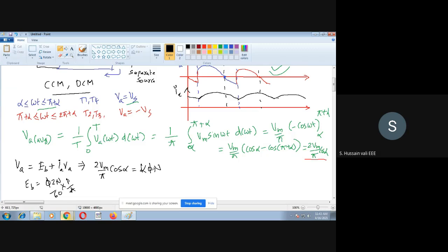So when the field is coming through a converter, then the voltage across the field may be variable. It depends upon the value of firing angle also. So better take it as k, where k is Zp by 60A. That is k. So we can take Eb as k phi n, plus Ia Ra. Will write like this only.